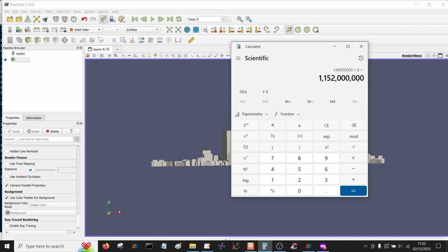I can run that on RunPod GPUs, but it could take 12 hours to run. I generally run the lattice Boltzmann solver for 100,000 iterations, so that you can see the development of the flow solution and all the unsteadiness. So that's quite a big case, and then that's going to cost you $4 an hour or whatever it is.